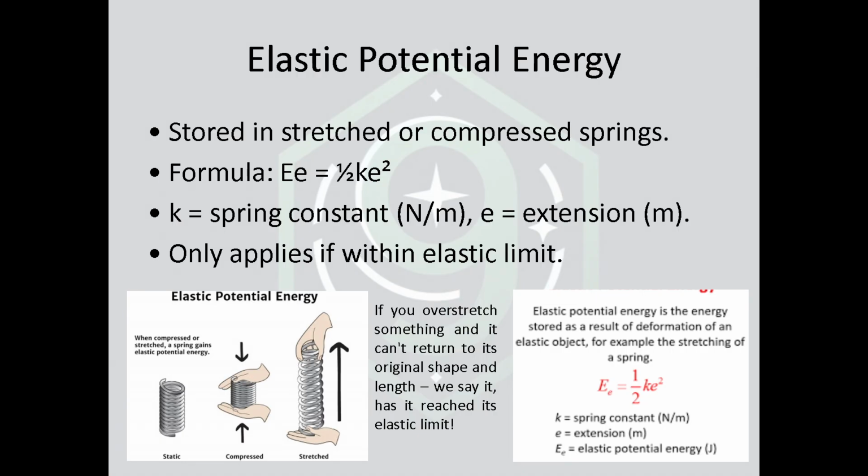Keep in mind a conversion trick may be here where they give you the extension in centimeters, so you would have to convert it to meters by dividing it by 100. And this only applies if it's within the elastic limit. So for example, if you had a string and you continued stretching it out, and then when you let go of it, it doesn't change back to its original shape, that means it's reached its elastic limit. You've deformed it and it won't return back to its original structure and shape.